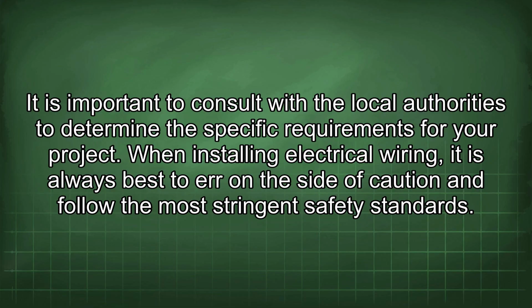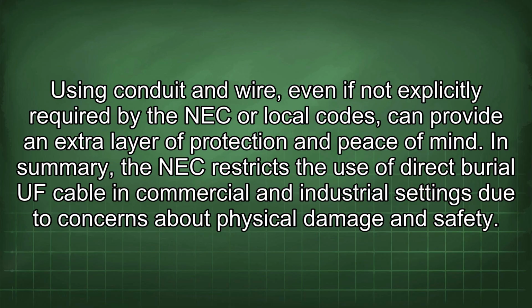When installing electrical wiring, it is always best to err on the side of caution and follow the most stringent safety standards. Using conduit and wire, even if not explicitly required by the NEC or local codes, can provide an extra layer of protection and peace of mind. In summary, the NEC restricts the use of direct burial UF cable in commercial and industrial settings due to concerns about physical damage and safety.